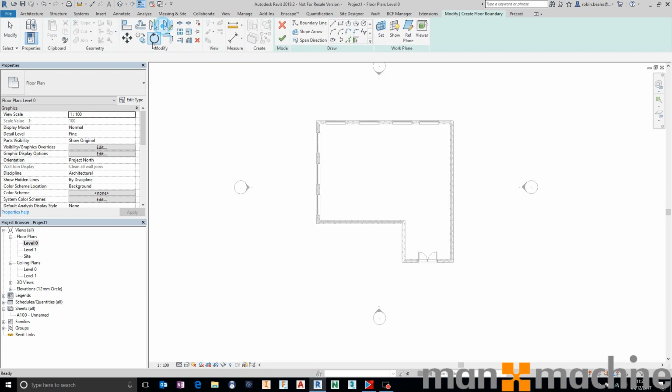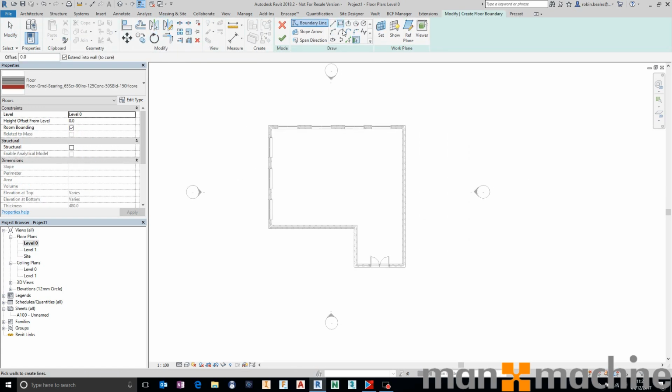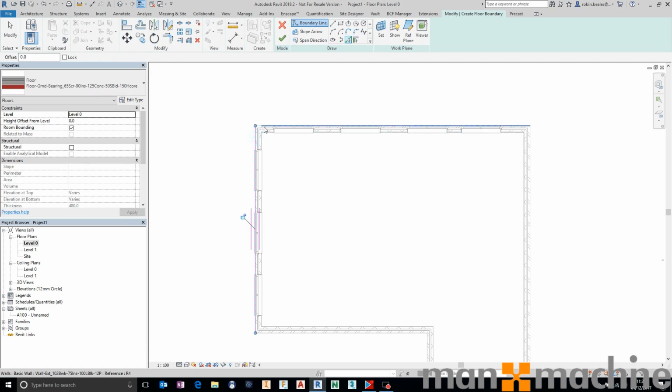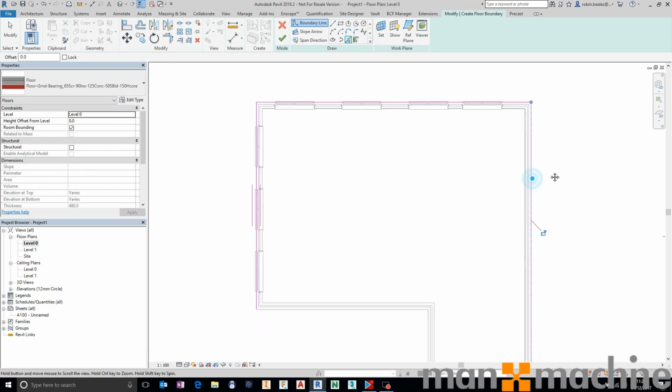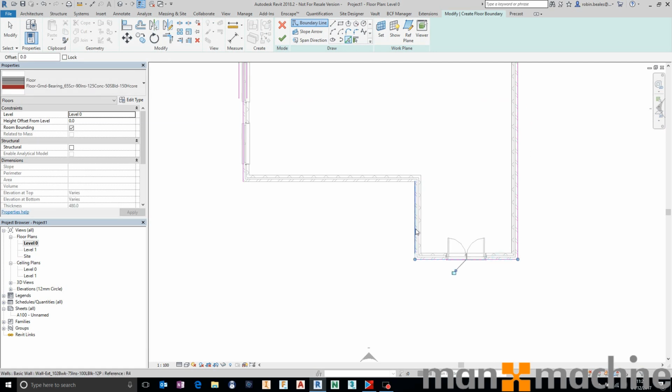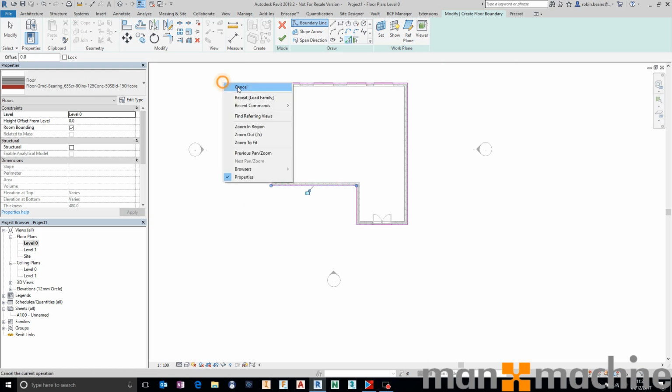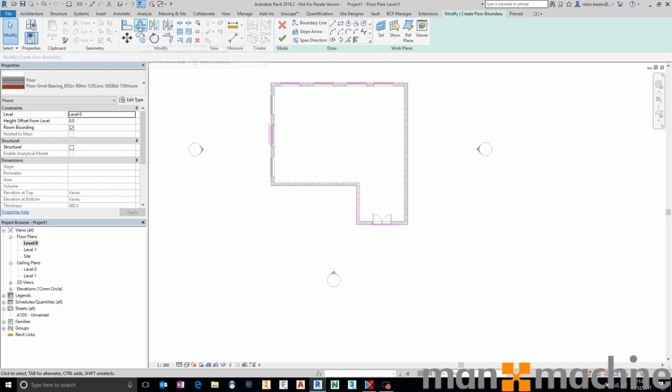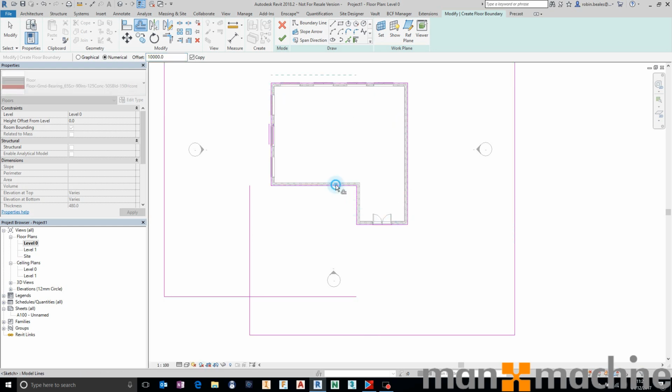I'm going to be very, very lazy. So I'm going to add a floor. I'm going to use the outside of the walls that we already have, just to go all the way around the outside of the building and then some more. You'll see why in just a second. So let's grab all of those. Let's then offset all of those by, I don't know, 5-10 meters is probably okay for this example, and just place them around the outside of the building, like so. Use a bit of trim to corner just to tidy those up.